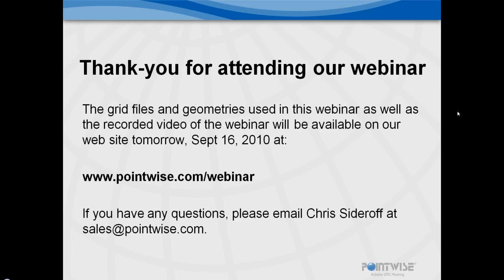There's a second question that came up about our topology in the rotor tip gap region. It says, I noticed that you have pole or singularity boundaries in the rotor tip. The question said near the fillet, but it's actually in the tip region. At the rotor fillet, at the hub, we do not have any pole or singular topology. However, in the tip gap region, there are poles or singularities running from the leading edge to the shroud and from the trailing edge to the shroud. And this was simply a simplification of topology in that case.